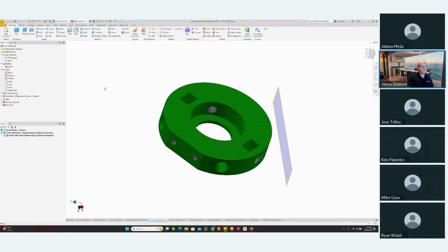It is great if I'm only going to do, let's say, a chrome finish on this face. Faces is great. But if I'm going to heat treat this part, it's going to be the whole part. It's not going to be just one face. Sometimes you do induction harden certain areas, but for the most part, if I'm going to heat treat something, it's the whole part, not just a particular area. So the faces is still necessary, but also solids.